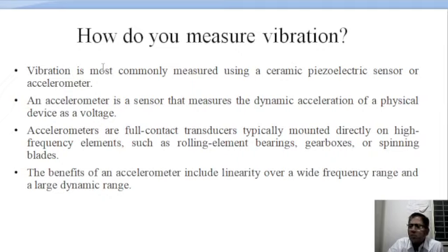So vibration is mostly measured by using a piezoelectric sensor. A piezoelectric material is a smart material which is made up of ceramic or quartz. It generates electric charge when it experiences a force on it. An accelerometer is a sensor that measures the dynamic acceleration of a physical device as a voltage.